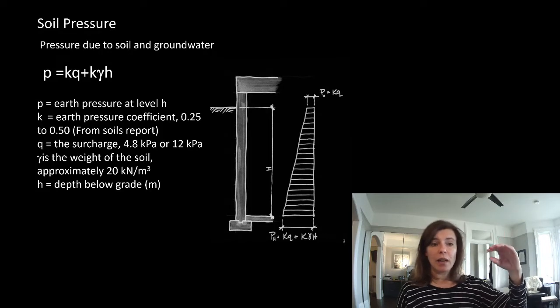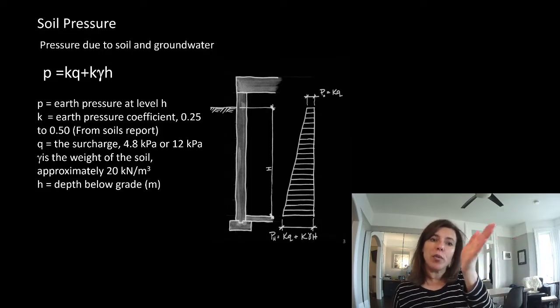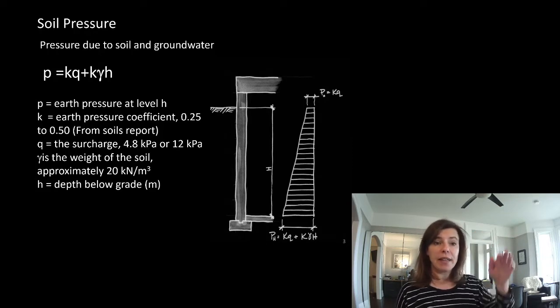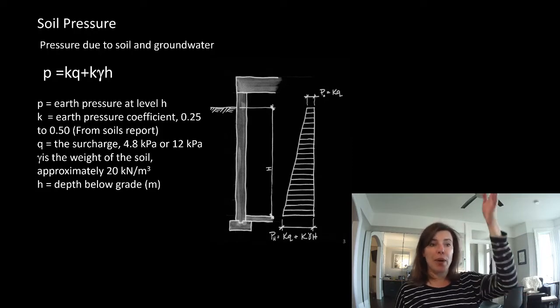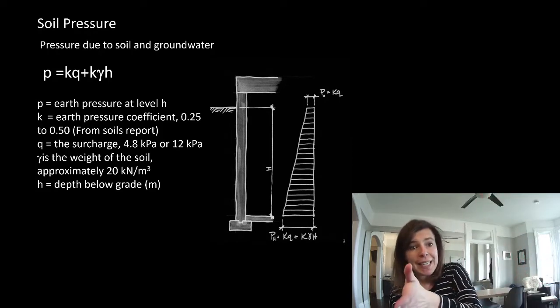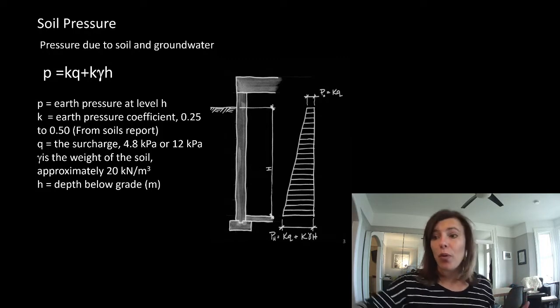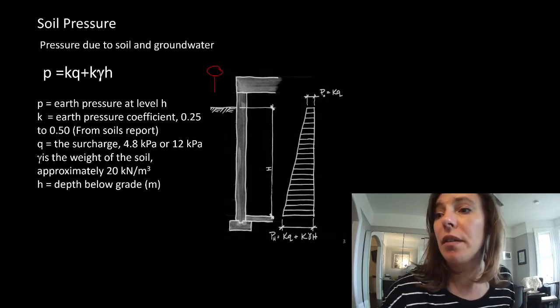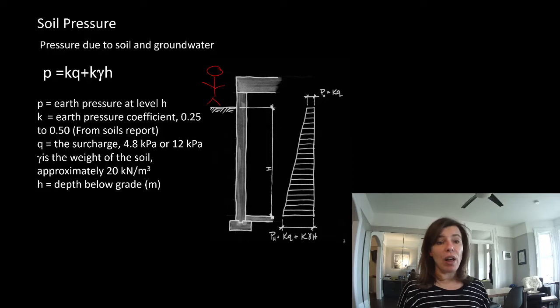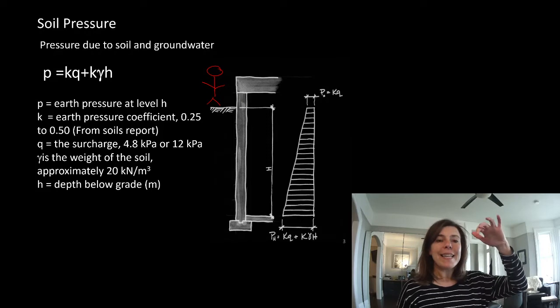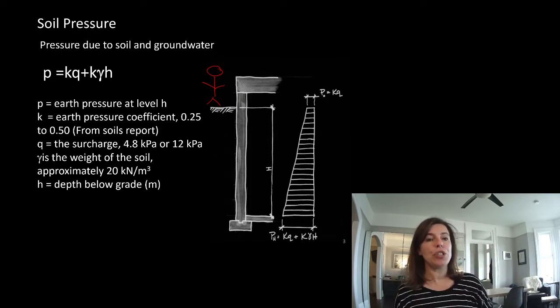Down just a little bit, there's the weight of the soil above, and we're trying to push in some fraction of that weight. As we go all the way down to the bottom of the foundation, we have all the soil up above, which means we're trying to push into our hole with some fraction or some percentage of that weight. And then, just like your pesky brother or sister, if we have a live load, or what we call a surcharge, on the soil right by that hole, it's adding to the weight that's trying to push into the hole.